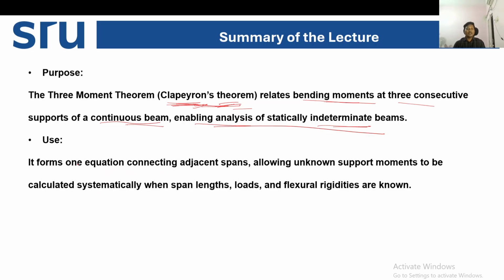What is the use of this three moment theorem? It forms one equation. That is important. That is the benefit of this method. It forms only one equation connecting adjacent spans and allowing unknown support moments to be calculated systematically when the span length, load, and flexural rigidity are known. So in that situation, we can use three moment equations to solve this particular problem in a simpler way.